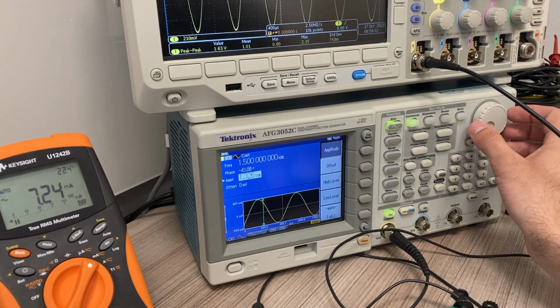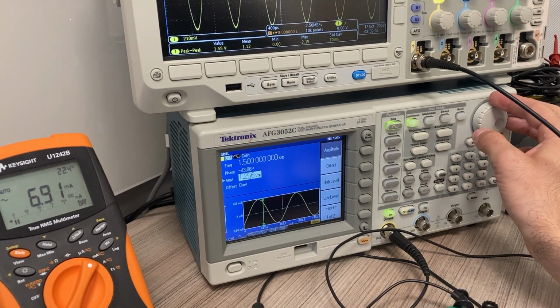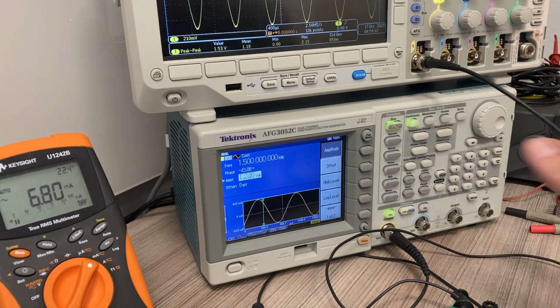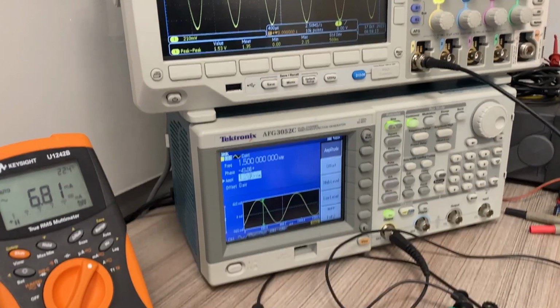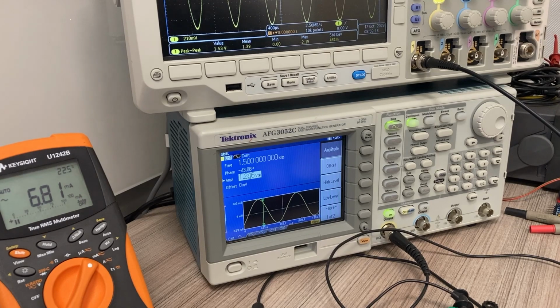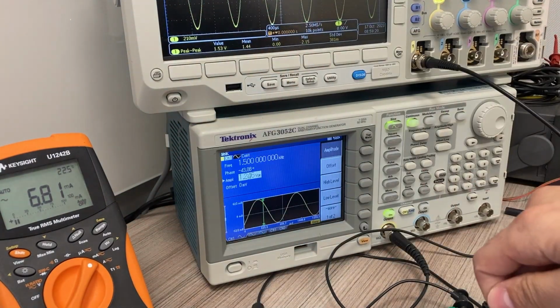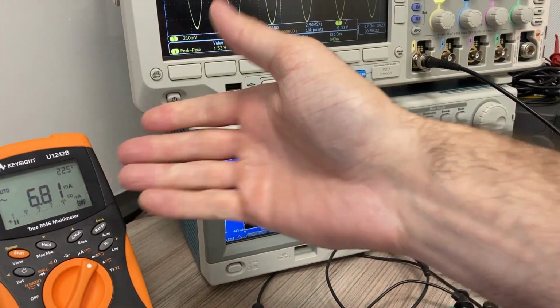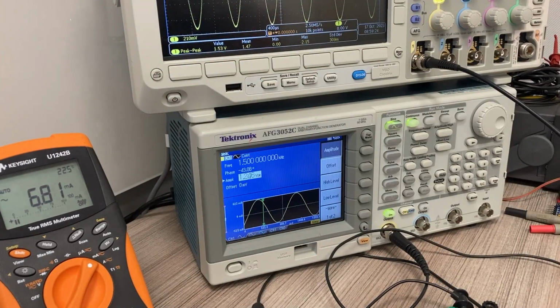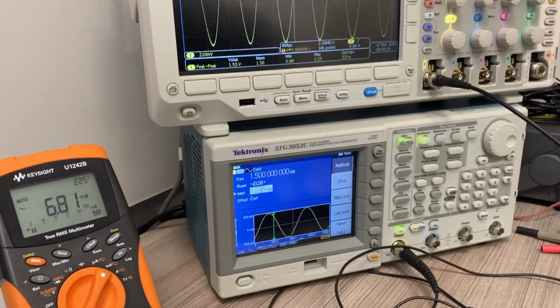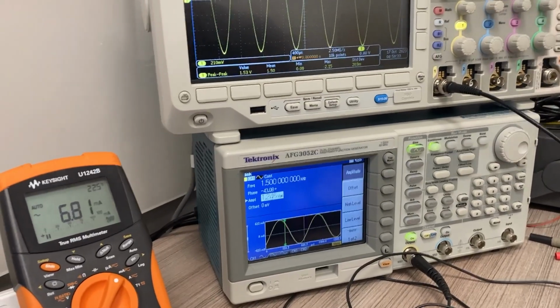Again, I have to adjust the voltage here to 1.53. And measure this, so 6.81 milliamps RMS. Of course, your current is always going down, right? As you increase the resistance, your current can only go down. But your power equation says 1/2 I squared R is the way you determine the power through the resistor. So that will not continue to go down.